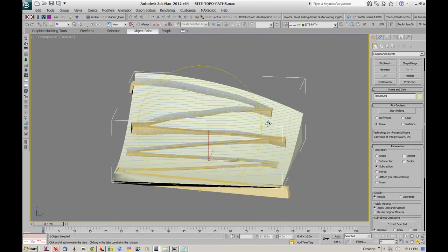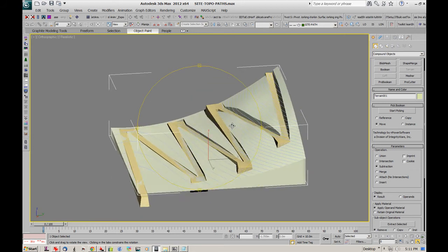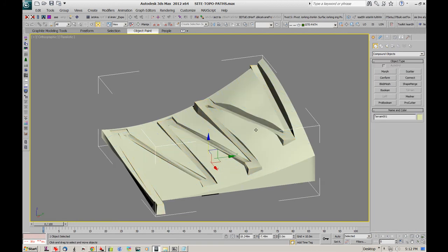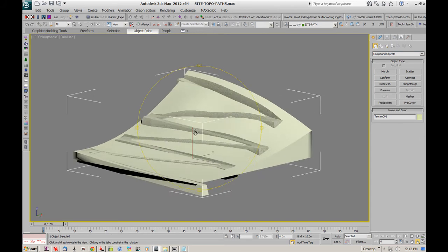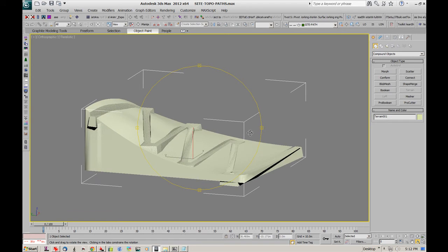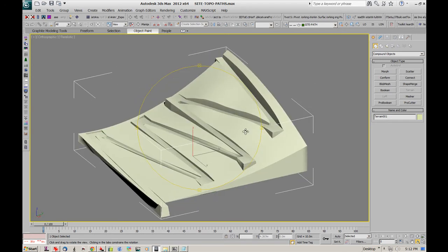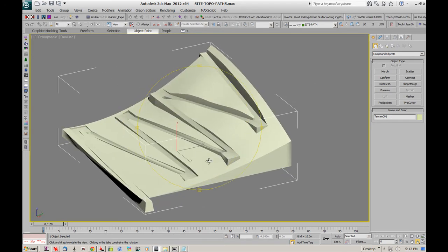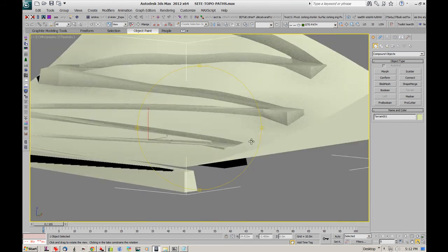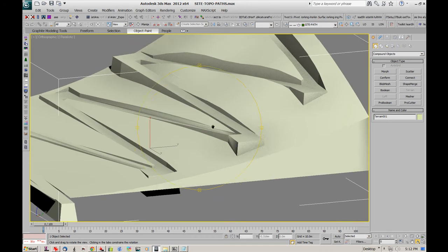You can see it's made a cut into this terrain. Then we'll do the add part, which we'll use union, and we'll pick this guy. Okay, so now we have a path that's been cut in and kind of added. Where the path is too high, it sits up above. Where it's too low, it cuts into the hill.